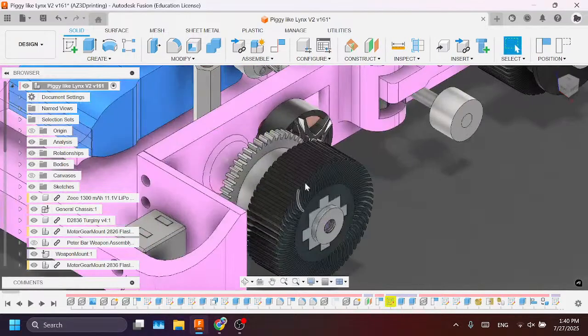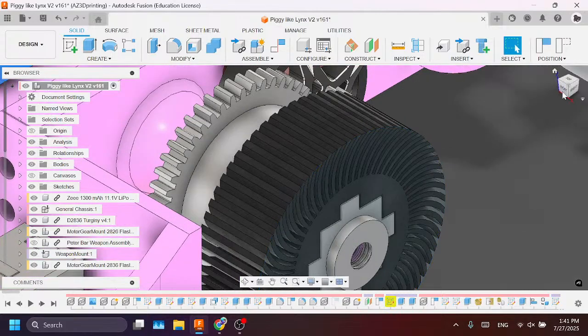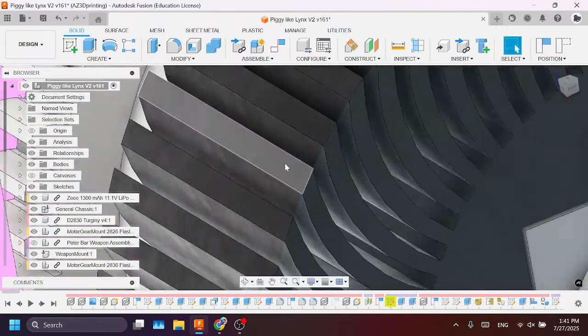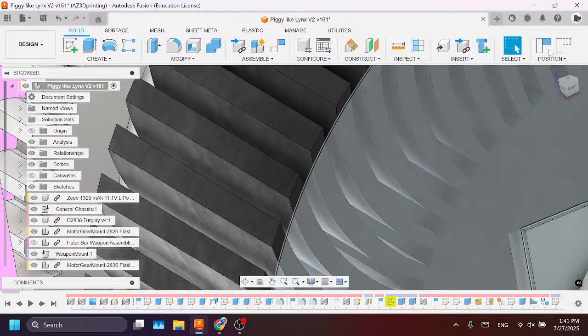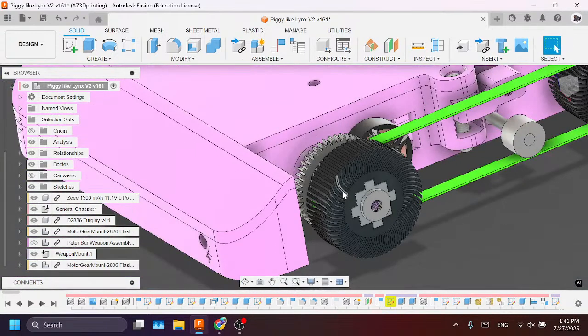So yeah, those are my TPU compliant wheels. I don't know if you guys saw it, but a while back Mark Rober, I'm sure you've heard of him, big YouTuber, made a video on compliant mechanisms, and this is basically the same thing. The TPU, which is a flexible material, is supposed to bend down a little bit, so it squishes down, and that gives it better traction theoretically.